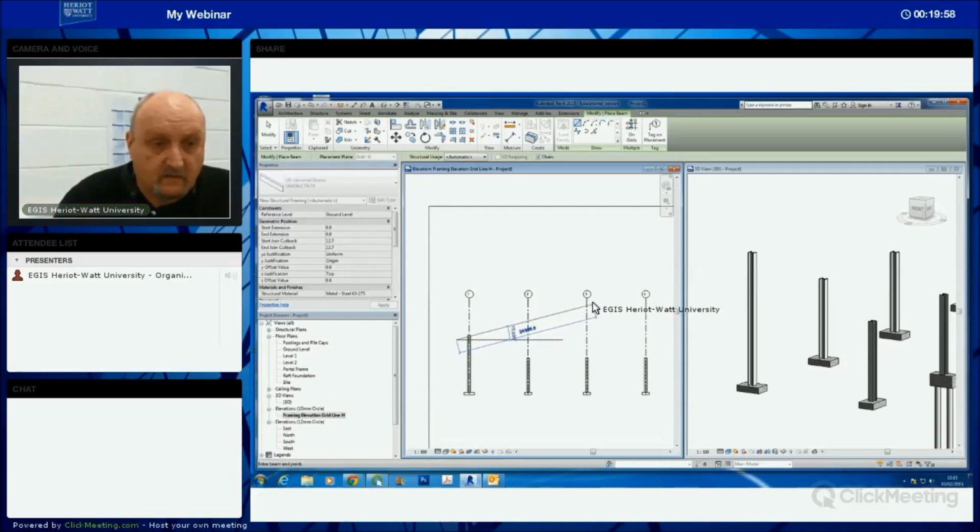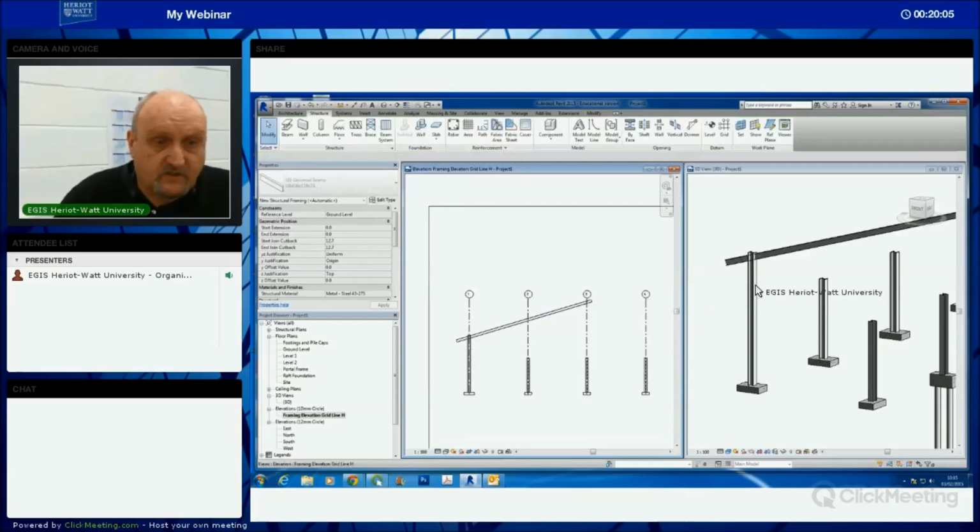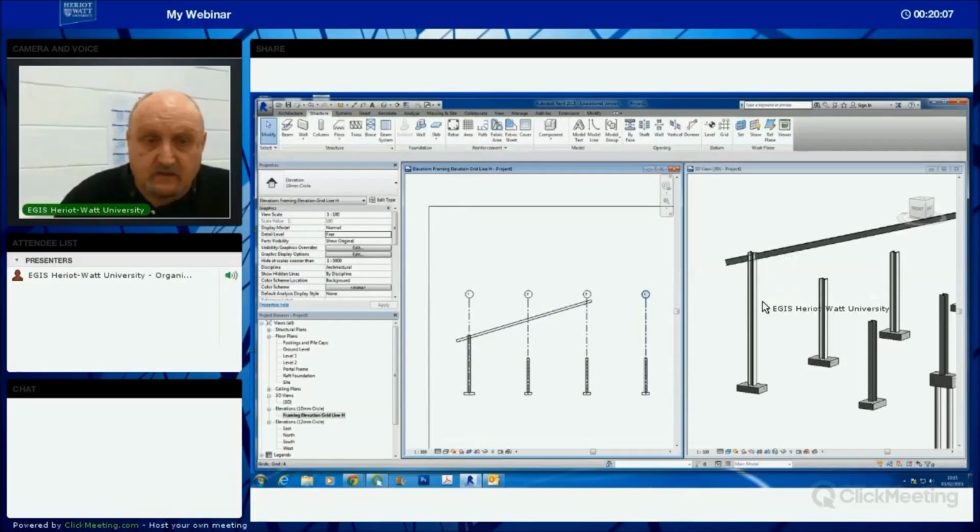This will vary, but I'm going to make mine 17. So click there, and you should see in the 3D view it's beginning to appear in here. I've got some changes to make in here. Clearly I've got to trim it down a wee bit, and I want to put in some haunches in here to give it additional support.